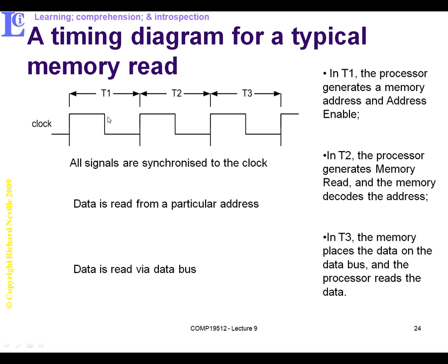The important thing to realize is the processor and its internal registers may be able to process information very quickly internally in one cycle, but normally outside the processor the system bus and the memory will be running at a slower rate. Therefore it will take a number of clock cycles to process data.